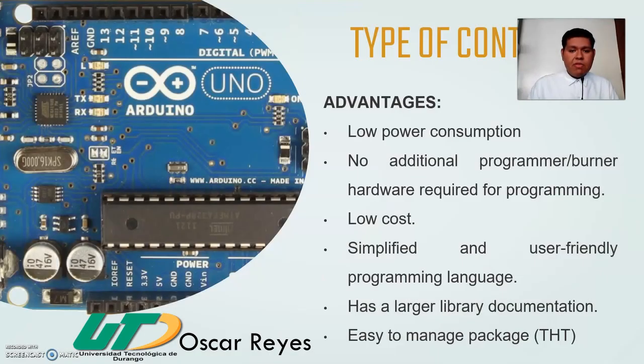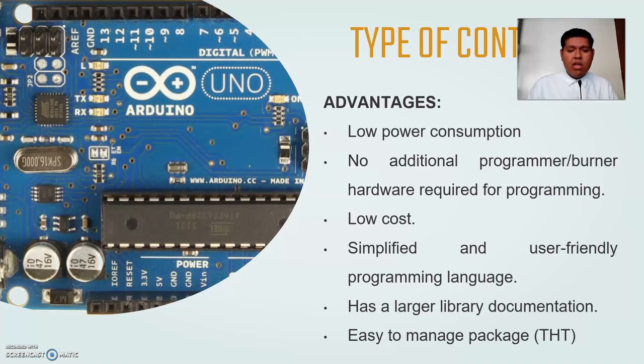First of all, the type of controller. In this case, we decided to use the Mega 328P microcontroller, which can be easily found in the Arduino Uno development board. The reason we decided to use said microcontroller is because for our project we required at least 8 digital pins, and this microcontroller has at least 14 digital pins, so it has more than enough. It also has the I2C communication protocol, which we required to use to communicate with the LCD to show error messages or the timer for the timer function that we decided to implement in our machine.